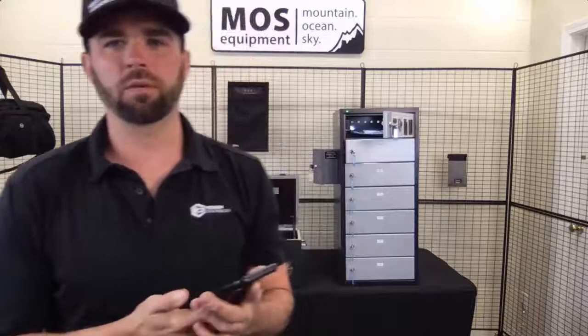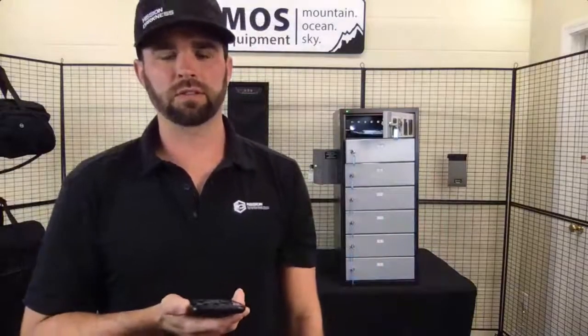Get really close to as high powered a Wi-Fi as you can, turn it on 5G, and do a 2.4 gigahertz test and a 5 gigahertz test using this. If it's going to block Wi-Fi, the chances are about 100% that it's going to block cell signals. So usually you only need to do a Wi-Fi test.